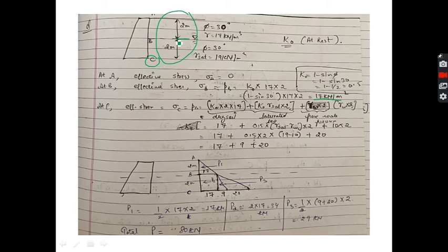So this will be a combination of both these parts. So sigma C will be sigma B plus this portion. Sigma B is K0 into 2 into 17 as calculated here, that is of dry soil, plus the saturated unit weight plus pore water pressure. As this is saturated, we will have two components, one of soil and one of water. So we get 17 plus K into gamma dash, which is gamma saturated minus gamma W, into 2, plus 10 into 2, where 10 is the unit weight of water. So we get these three separate values. This is for dry weight, this is for submerged weight, and this is for pore water pressure. I have written these individually so that it's easier to make the diagram.